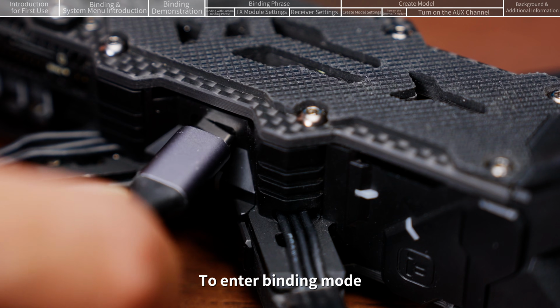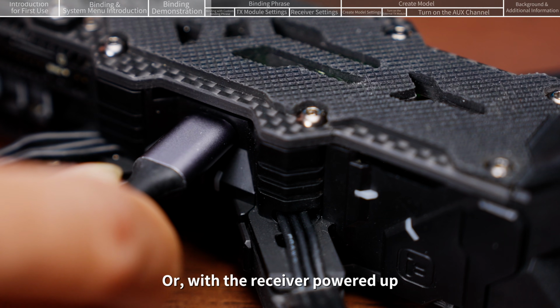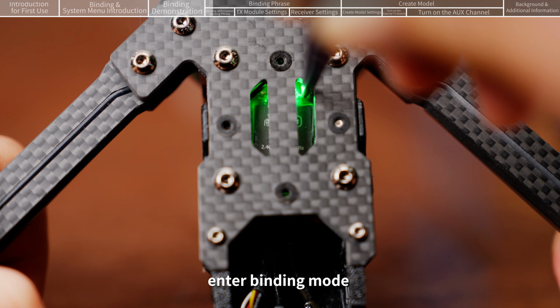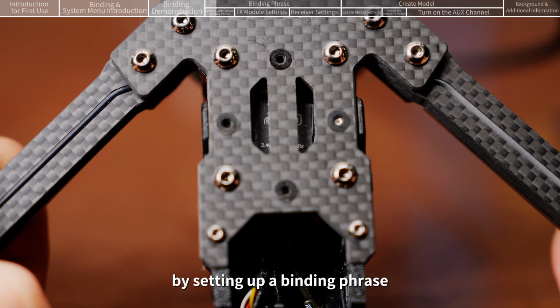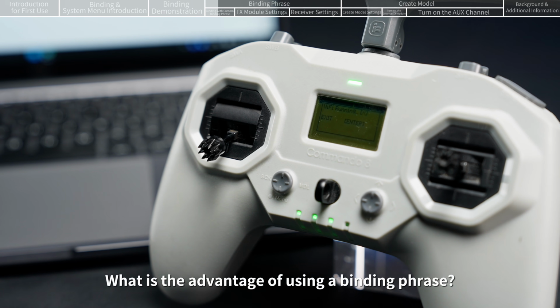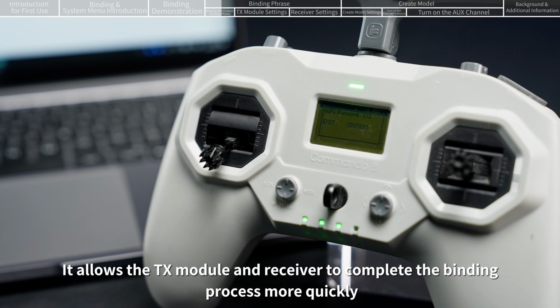Binding with custom binding phrase. To enter binding mode, besides the standard approach of cycling the receiver's power 3 times, or, with the receiver powered up, pressing and holding the boot button, we can also perform binding by setting up a binding phrase. What is the advantage of using a binding phrase? It allows the TX module and receiver to complete the binding process more quickly.